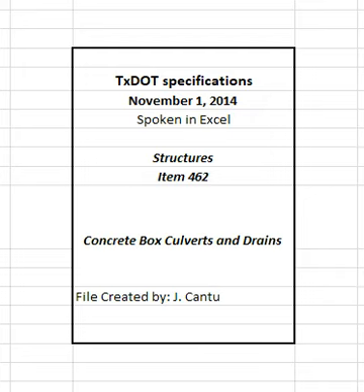Ensure precast sections meet the permissible variations listed in ASTM C1577 and that the sides of a section at each end do not vary from being perpendicular to the top and bottom by more than 1/2 inches when measured diagonally between opposite interior corners. Ensure wall and slab thicknesses are not less than shown on the plans except for occasional deficiencies not greater than 3/16 inches or 5%, whichever is greater. If proper jointing is not affected, thicknesses in excess of plan requirements are acceptable.